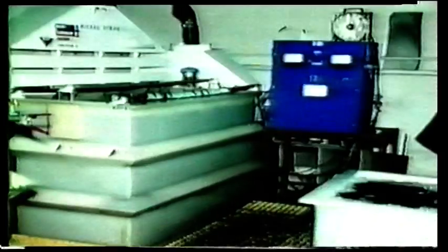Ask the facility representative what operations are conducted in the facility and determine if inherent hazards to the potable water supply exist. For example, some fish processing facilities use an iodine compound as a sterilization medium. It is pumped throughout the plant to sterilize process machinery, workers' hands, and instruments. An electroplating facility uses process tanks containing highly toxic chemicals. Water is added to these tanks from below or above the flood rim. Those filled from below constitute a cross-connection. The survey team needs to ask questions that will provide this type of information.